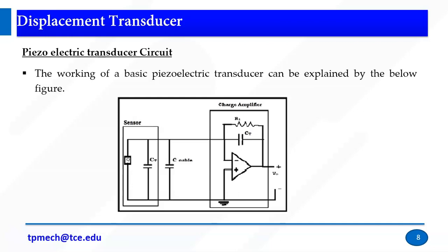So the quartz, we have given a silver coat on it, and we have connected it to the charge amplifier through capacitance. So now, for which metal can I measure displacement? For example, I am going to measure the displacement of the object A, right? So I am placing the object A, and on top of object A I will place this quartz crystal, this setup. So for whichever object I need to measure displacement, I am placing that device on that object.